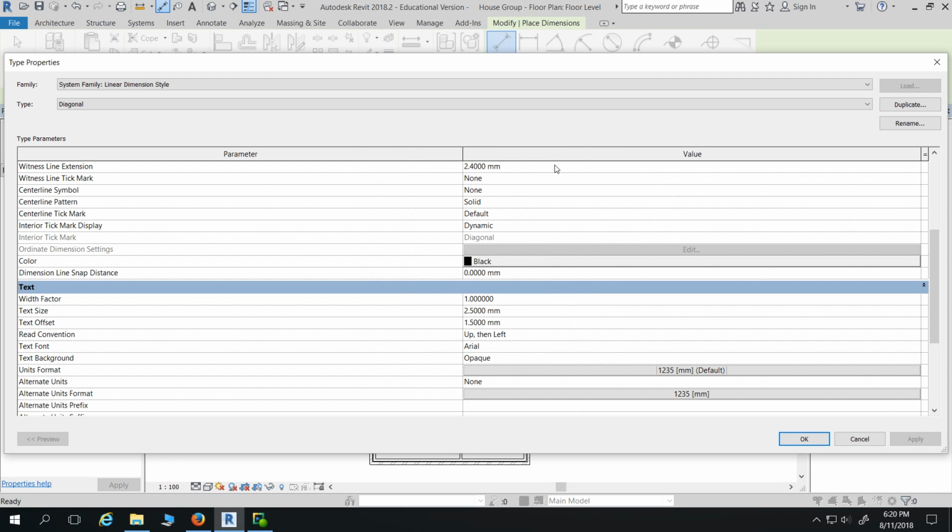In CAD, you can get around putting funky dimensions in, like it might be 5 meters, 0.92 millimeters, not 500. In Revit, if you start doing that, you'll get 501 because it'll round up to the nearest. So just keep in mind the CAD files you get from other people who have drawn them, they may not be super accurate. Just keep that in mind.